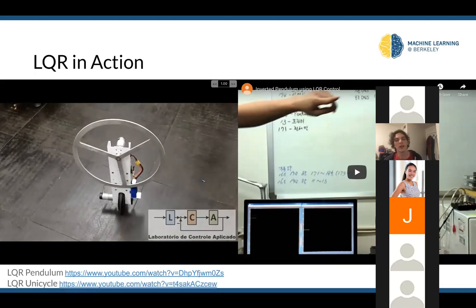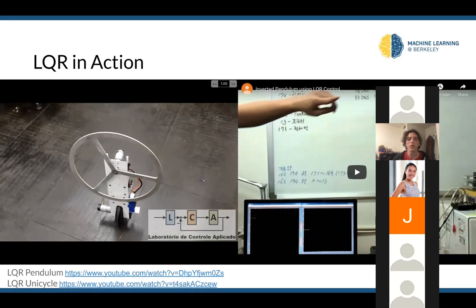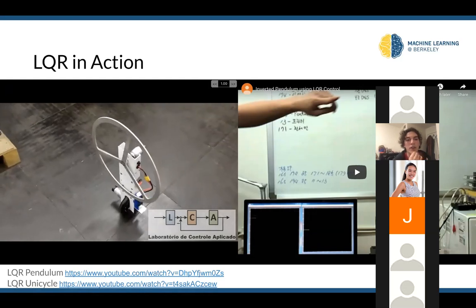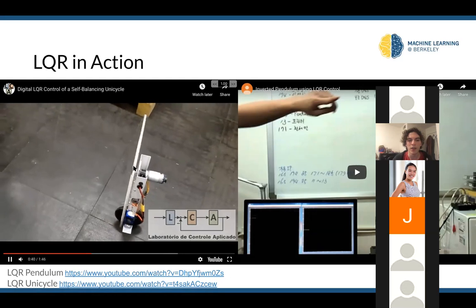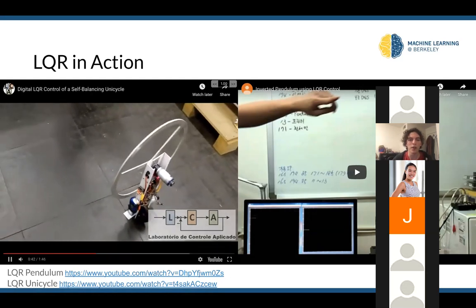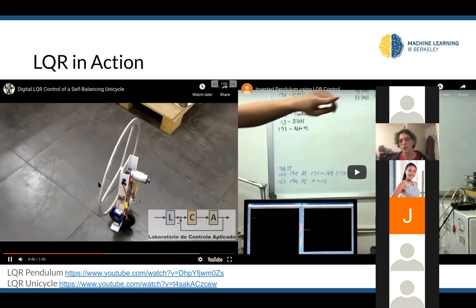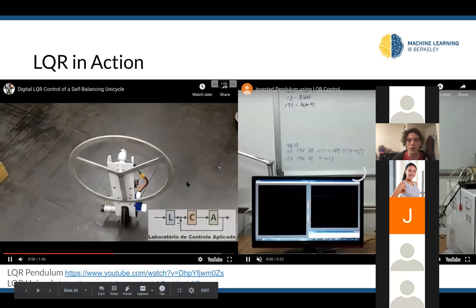And this is sort of an exaggerated system. In the car, it's not as difficult if we have a trajectory, but there's a lot of work to be done between having a trajectory and executing it. And LQR is what does that. So just by trying to minimize the cost function and getting to the goal state, there's a lot of real-time corrections that need to be done as you read in from sensors and update your state. And this is what LQR is good for.